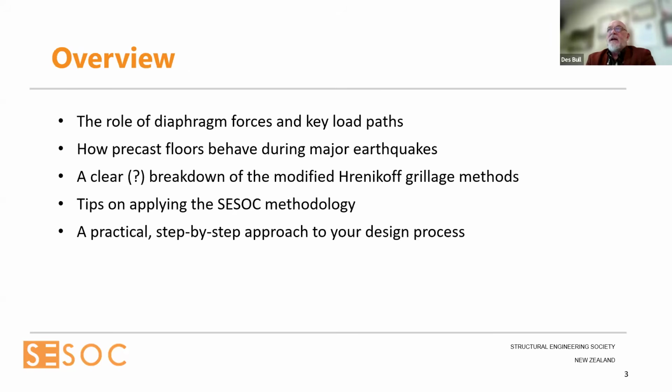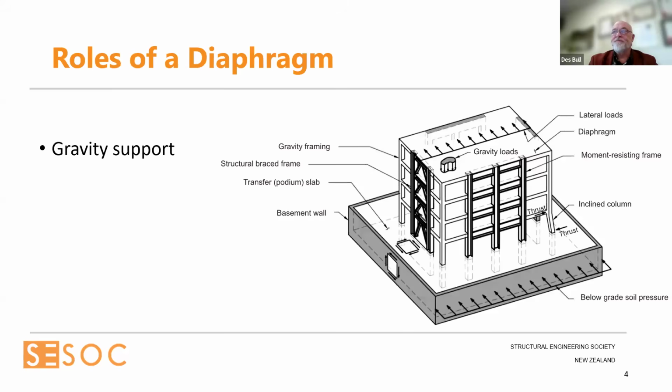What we're going to cover today, relatively quickly, is the role of diaphragms and diaphragm forces and key load paths, how precast floors behave during earthquakes, a clear, hopefully, breakdown of the modified Hrenikoff method for the grillages, tips on how to apply SESOC's methodology, which is out of Yellow C5, and a practical step-by-step approach to the design process, which I think will be familiar to all of you.